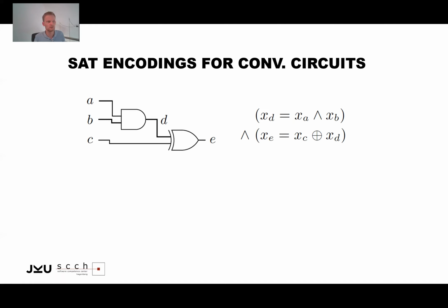And then what you simply do is you take encodings like that, you add corresponding constraints, for example, a miter structure, in order to make sure that if you have two circuits, the inputs are assigned the same and the outputs check whether or not they now realize different output values. And then you take the circuit encoding, you formulate your design task, and then you pass it to a SAT solver. And then the SAT solver determines a corresponding assignment. And out of this assignment, you can then conclude or derive the solution to your design problem.